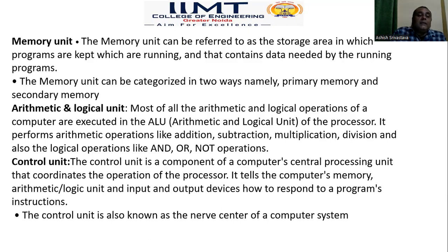So let's look at another one, the arithmetic and logical unit, ALU. ALU plays a very important role in the CPU. Most of the arithmetic and logical operations of the computer are executed in the ALU. It performs arithmetic operations like addition, subtraction, multiplication, division, and also logical operations like AND, OR, NOT. It means the ALU performs both types of operations, arithmetic as well as logical. Here are the two combined, so it is called ALU, arithmetic and logical unit.